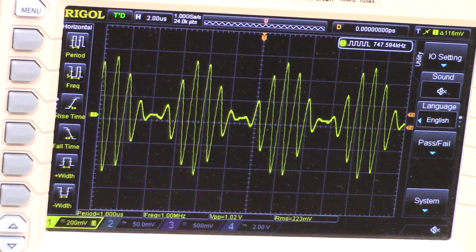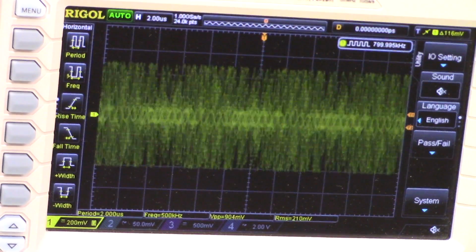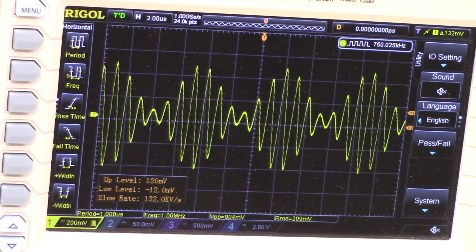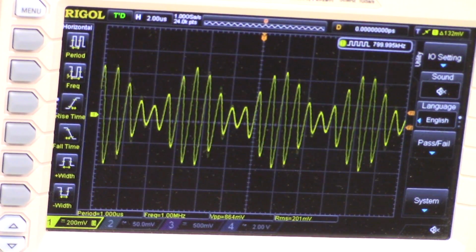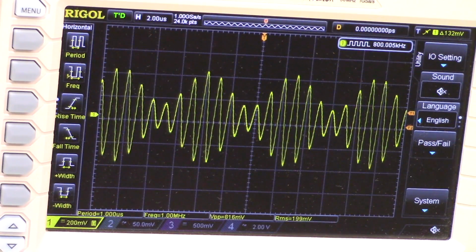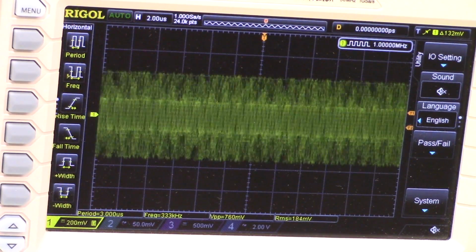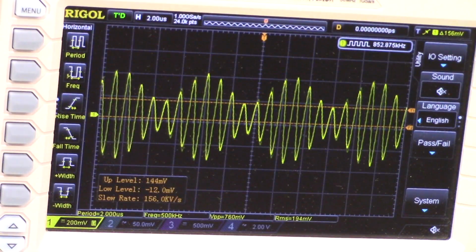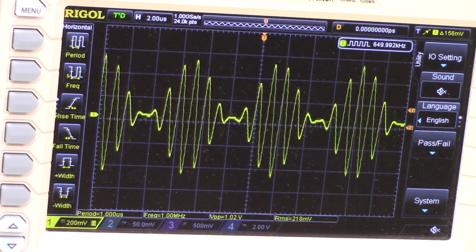Okay, so there is 100% amplitude modulation, and what I'm now going to do is dial that down. So there's 90%, 80%. You see my triggering needs to be adjusted. That'll happen again here. There's 70, 50% amplitude modulation. There we go. And so on and so forth. So let me dial that back up now to 100% amplitude modulation.